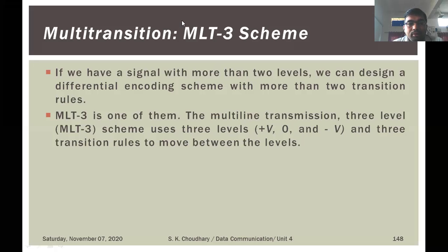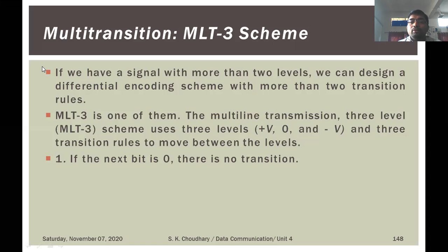If we have a signal with more than two levels, we can design a differential encoding scheme with more than two transition rules. And one of the multi-transition techniques is MLT3. So the multi-line transmission, three level, MLT3 means that there are actually three levels. Schemes having three levels like plus B, 0 and minus B, and three transition rules to move from one level to another level.